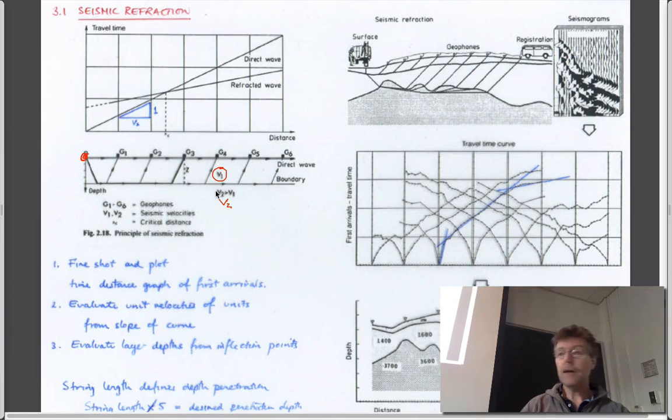Typically, as you go deeper in the ground, the rocks are more compact and denser, and therefore the velocity on the lower stratum would be greater than the upper one. So in other words, the pulse in going from this point to the geophone on the surface, where it will start shaking it, can either go this way, the shortest path, but through the slowest medium, which might give you a first arrival, or it can go through the slow material into fast material and go in that fast material for a certain length and then kick back up through the slow material.